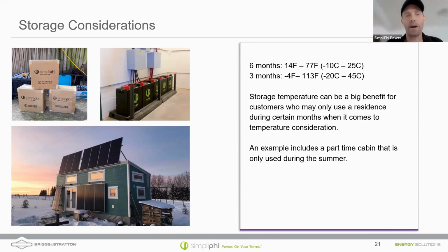Unlike lead acid batteries, which discharge really rapidly when they're stored, lithium batteries typically only lose about 1% state of charge per month. So they're going to stay charged up. I was at a facility in Florida where somebody had bought some batteries and they just had them sitting in a warehouse for a couple of years. We tested the state of charge and still after 2 years, they were at 92% state of charge. So lithium batteries maintain a charge a lot longer.